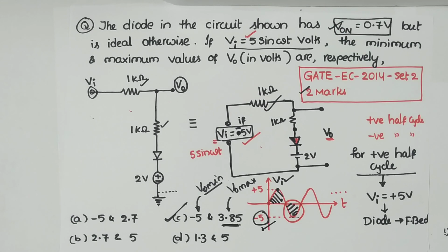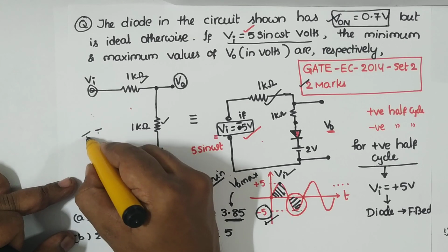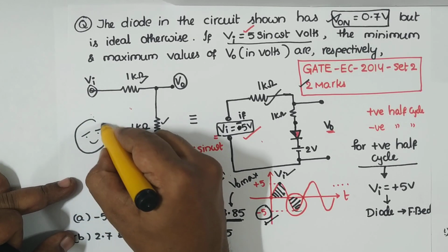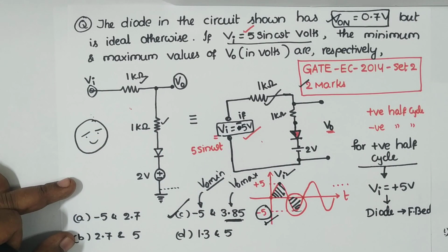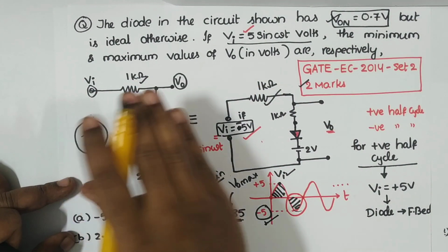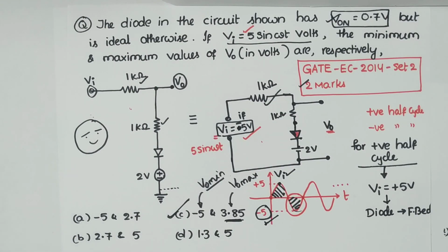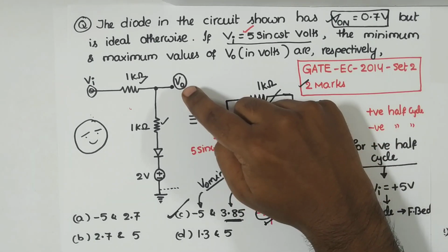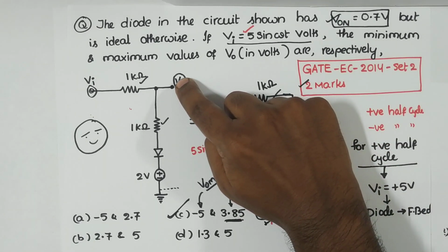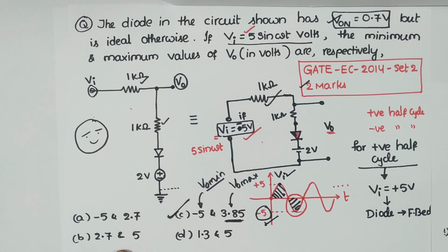That's it for today. This is a simple and interesting question as well. Whenever you're given this kind of question, if you have doubts, please try to redraw your circuit in your convenient way. Then you can try to solve. Definitely it will help. Node voltage must always be with respect to ground. That you have to understand in the initial run. Then you can do things very well.